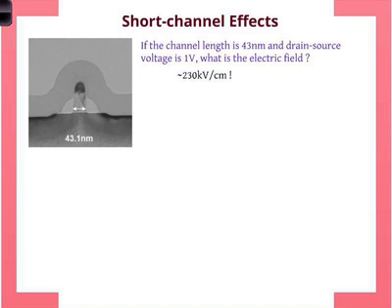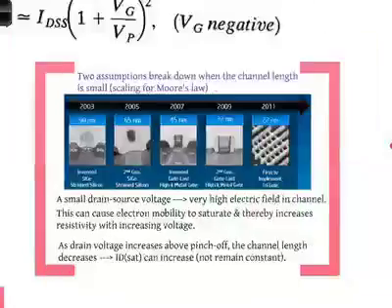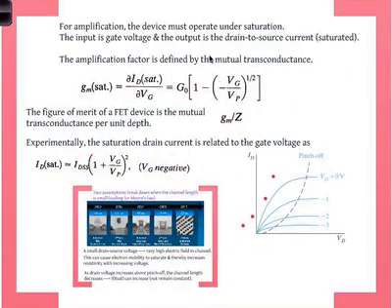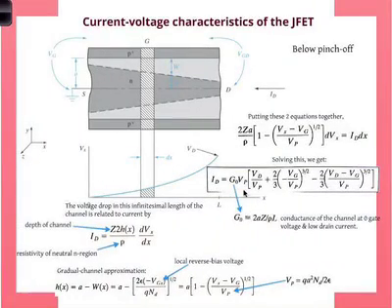But we know, and we saw in our previous lecture, that if the electric field is too high, this is no longer true. Mu is no longer constant. It depends on the field, which means that the velocity will start to saturate. Once that happens, all these equations that we did are no longer valid. Actually, the transconductance too. Why? Because we assumed this thing to be a constant.